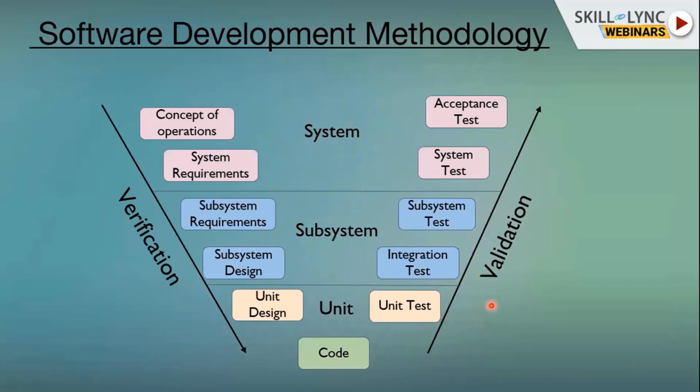And how one would go about using the V model for designing. The software development methodology using the V model has a verification segment. You take the requirements and break them down into multiple requirements. Just saying autopilot design does not mean anything. You have to specify an aircraft, a sensor suite, and an actuator, and then talk about the autopilot.